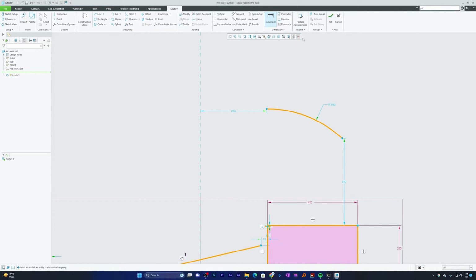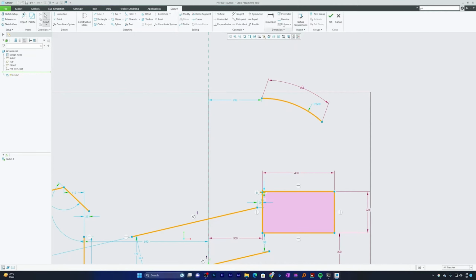I need to press this dimension button, and now simply select the dimension and choose both these endpoints, and then simply press the scroll wheel on the top side, and in this way, guys, we will be able to get this arc length. So this method is not so common and easy to find. So I hope that this tutorial will give you some extra value by knowing those techniques which are not commonly available or not commonly used.